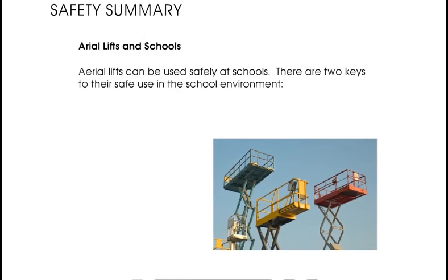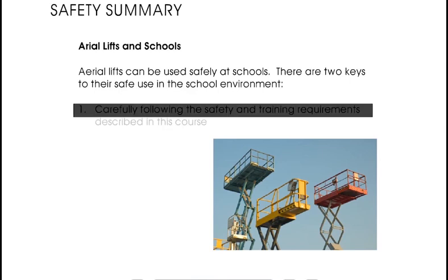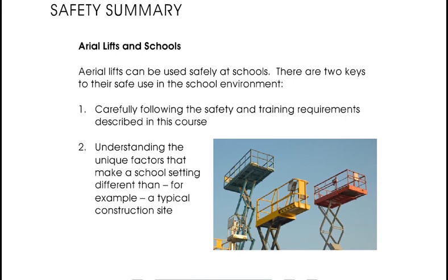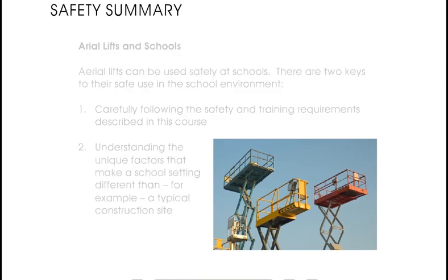Aerial lifts can be used safely at schools. There are two keys to their safe use in the school environment. Carefully following the safety and training requirements described in this course, and understanding the unique factors that make a school setting different than, for example, a typical construction site.